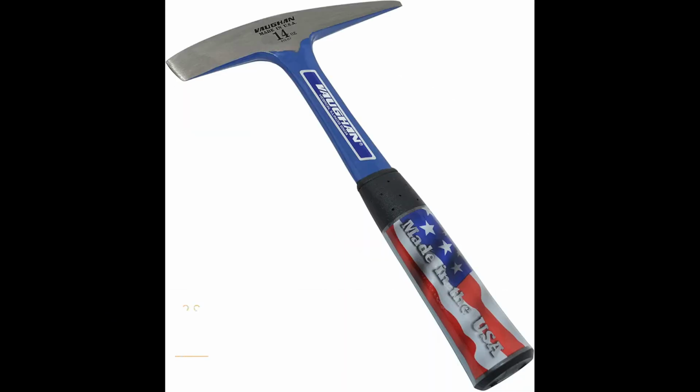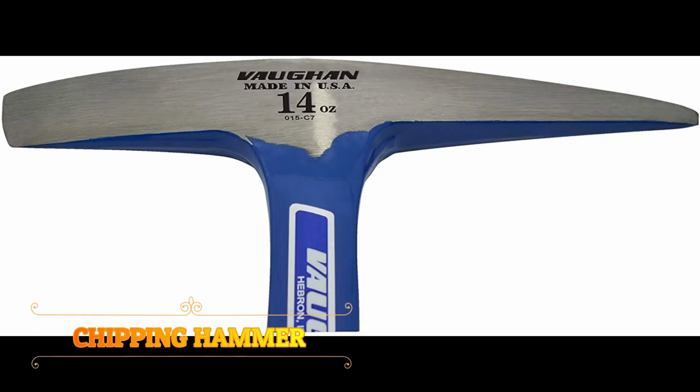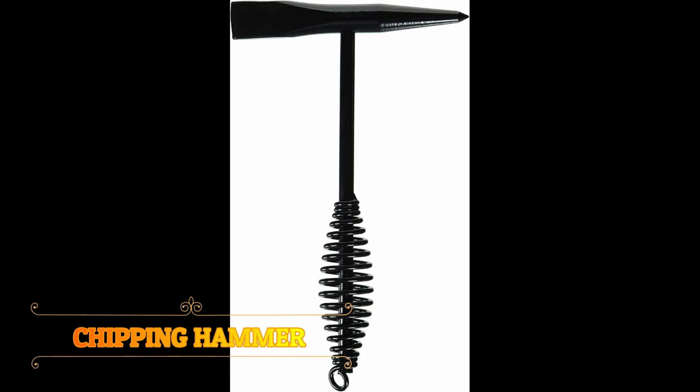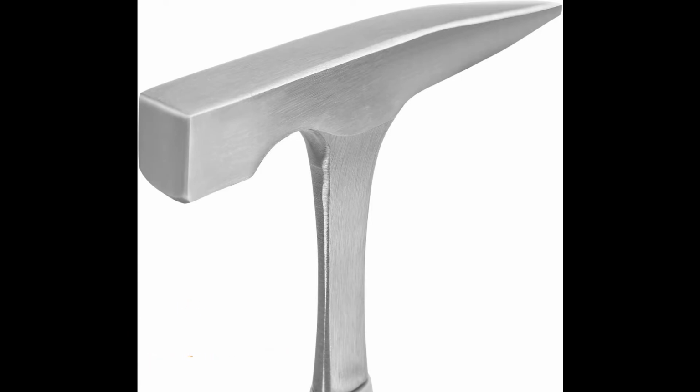The next one is chipping hammer. The chipping hammer is used for the removal of slag after arc welding. The hammer is of robust construction and well balanced. When working on stainless steels, a chipping hammer made of stainless steel must always be used.